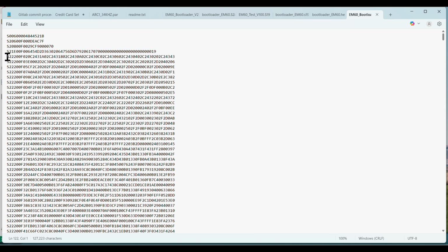The way it works is here it says, okay, this is an S2 command. So again, S record here, and then type 2, which is download some code. Then the next one here, 1E, is how many bytes are there. And then we have the start address, in this case 24 bits, therefore 3 bytes, where that is going to get downloaded to, then all the data and the checksum.